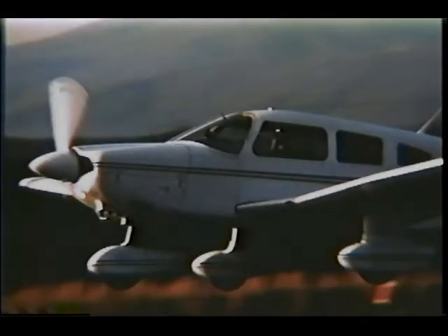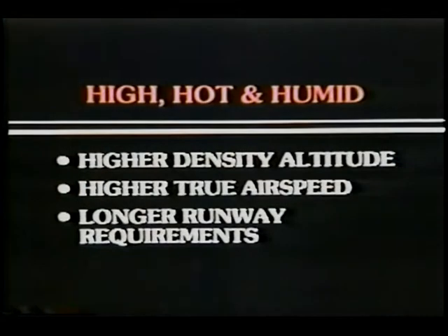Density altitude doesn't have a whole lot of impact on landing rollout, the way it does on takeoff performance. But pilots should never forget that high, hot, and humid means higher density altitude, higher true airspeeds, and therefore longer runway requirements for takeoff as well as for landing.